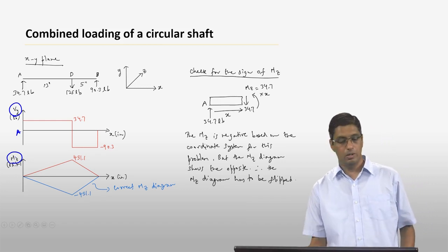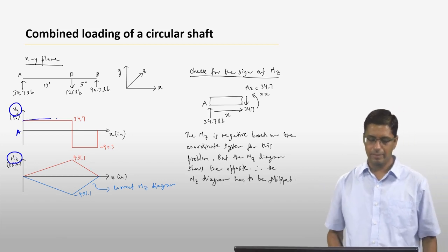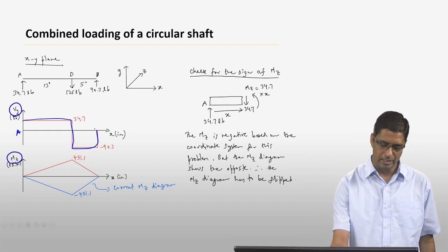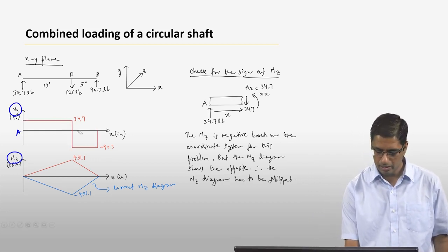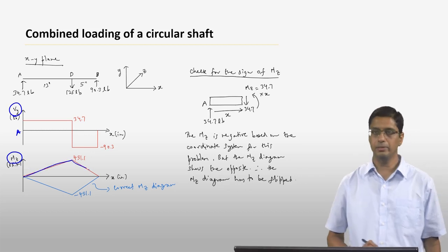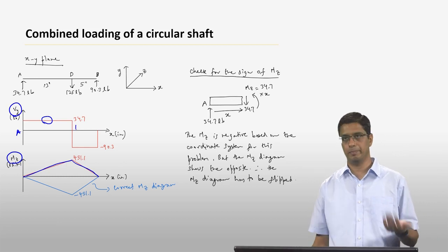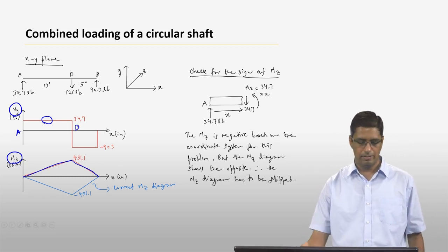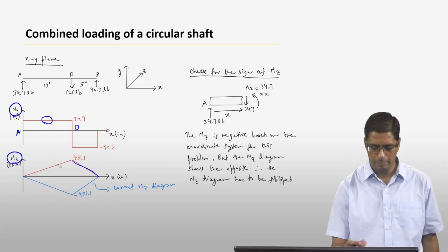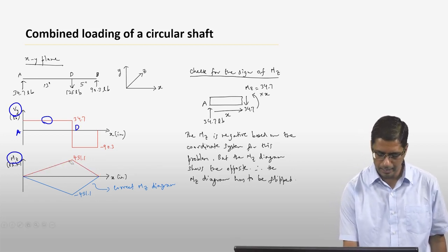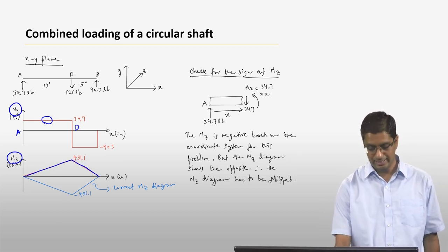Okay. Now, we already have the shear force diagram as it is here. Okay, and from that, if you construct the moment diagram, it will essentially look like this, because your shear is positive from A to point D, which means that the slope of the moment has to be positive. Now if you do that, you will essentially have a diagram that looks like this. Okay, that goes up from A to D and then goes down from D to B. Okay, now is that the correct diagram?